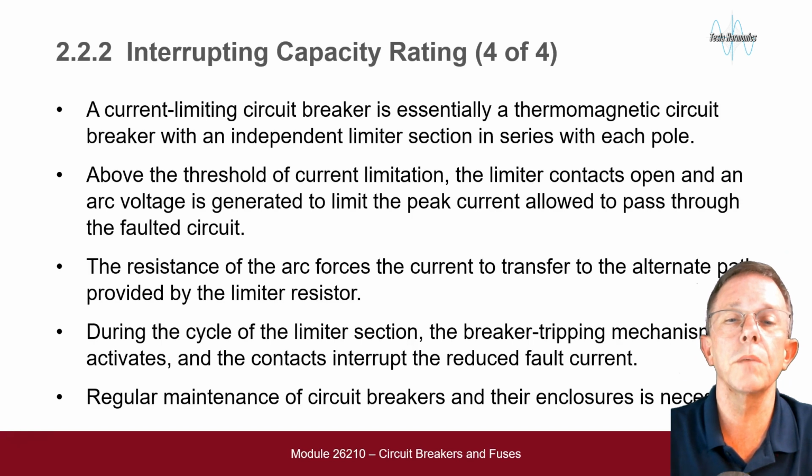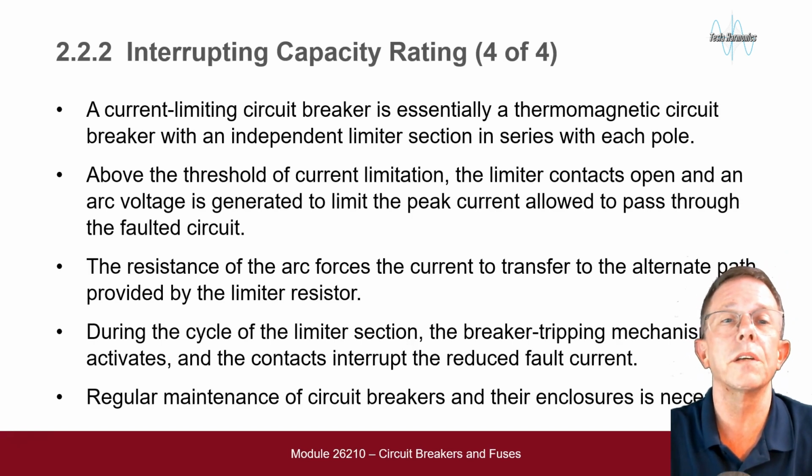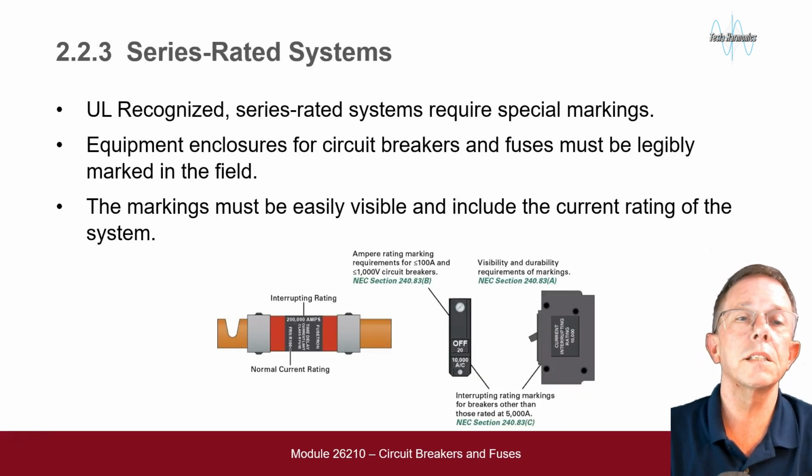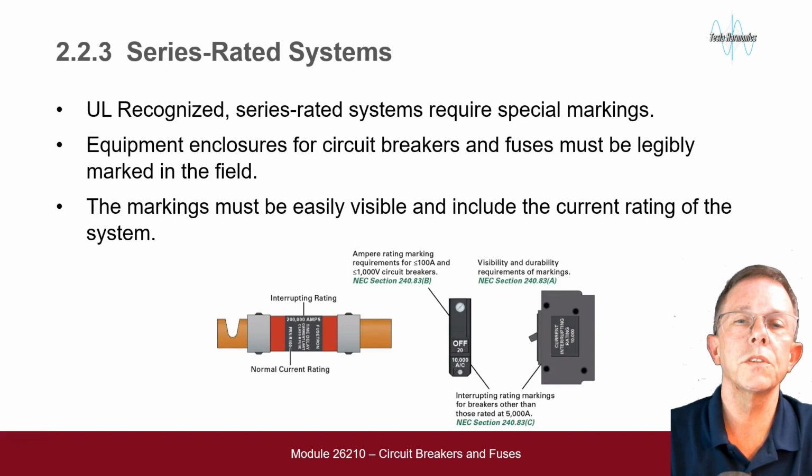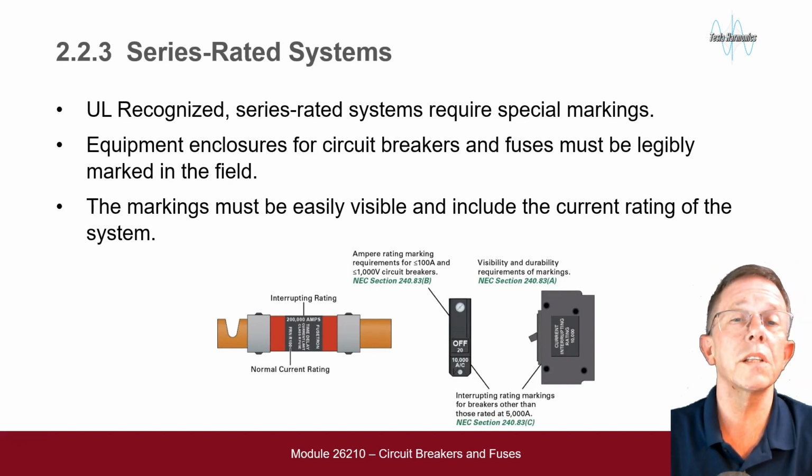Regular maintenance of circuit breakers and their enclosures is necessary. Series rated systems: UL recognized series rated systems require special markings. Equipment enclosures for circuit breakers and fuses must be legibly marked in the field. The markings must be easily visible and include the current rating of the system.